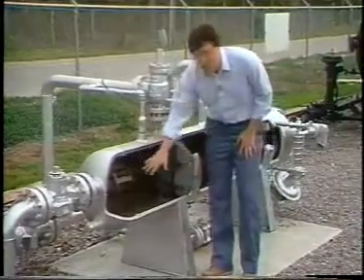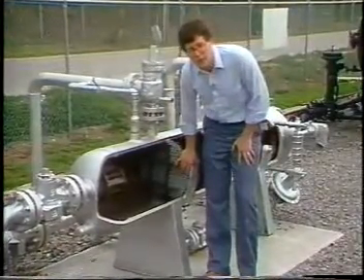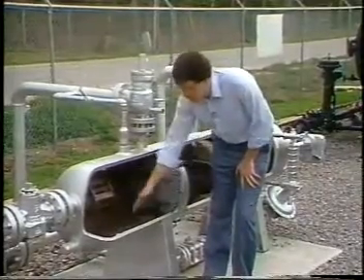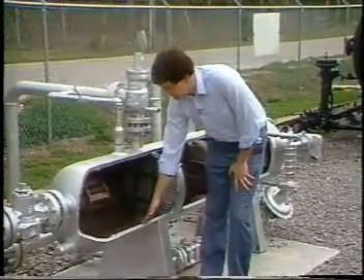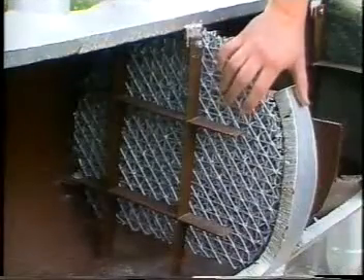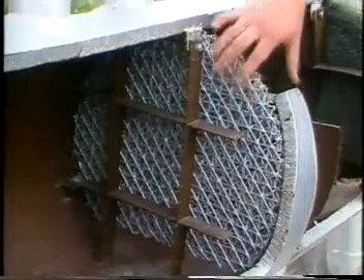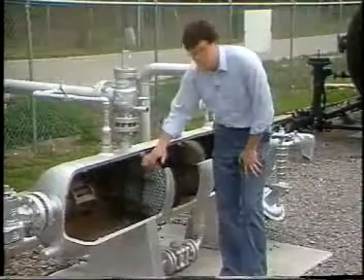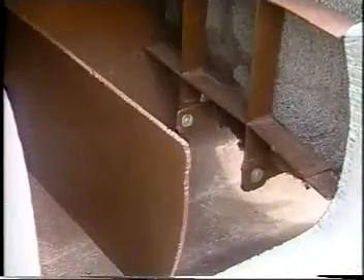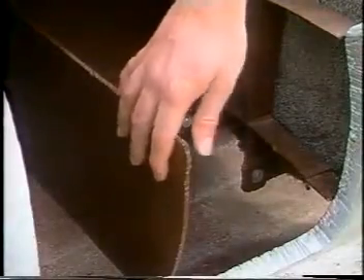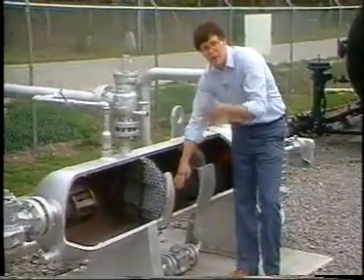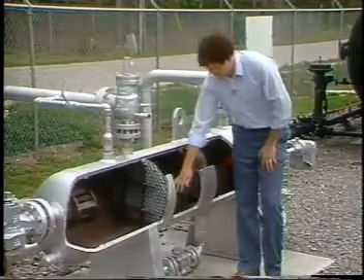This liquid settling portion of the separator here needs to be sized to allow enough time for the oil to begin to form a pad on top of the water layer at the bottom of the separator. The gas, of course, comes to the top of the separator. In this particular vessel, we also have some grating here which acts as straightening vanes to smooth out the flow of gas and liquid through the separator. Next, we find a wave breaker that prevents any surges of liquid from forming waves that flow horizontally through the separator that might re-entrain gas into the liquid phase at the bottom.